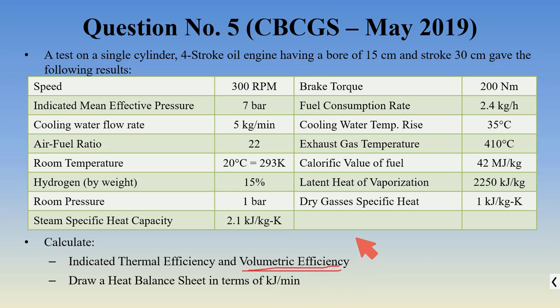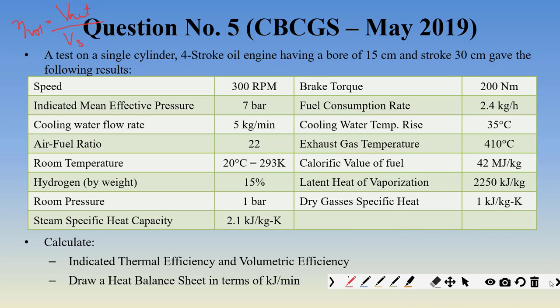Till now, in no question had they asked us to find the volumetric efficiency of the engine. But in this question, they have asked us to find the volumetric efficiency of the engine. By now you should know what volumetric efficiency is. I have explained it several times. Still, I will explain it once. What is volumetric efficiency? Volumetric efficiency is the volume of actual amount of intake air divided by the swept volume, right? How did we get this?